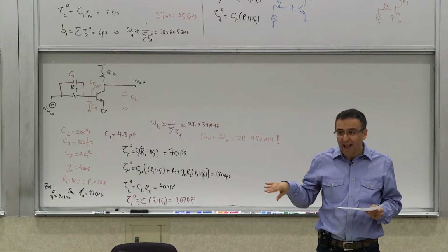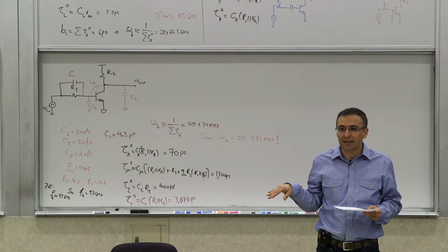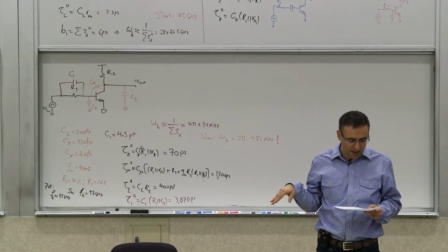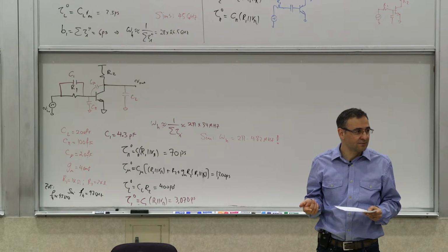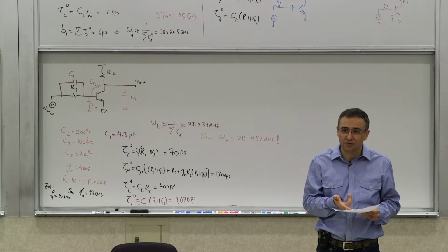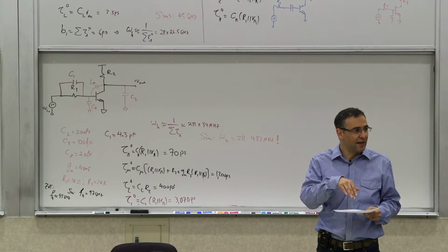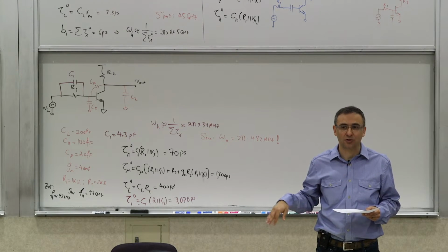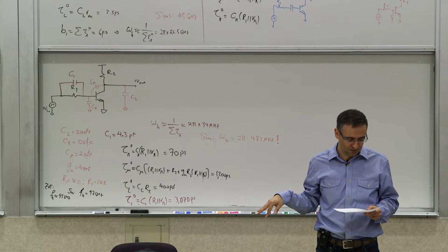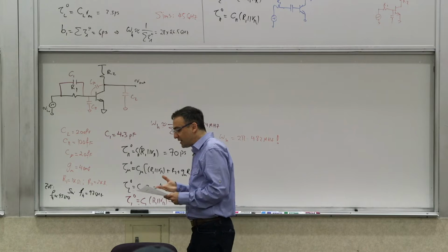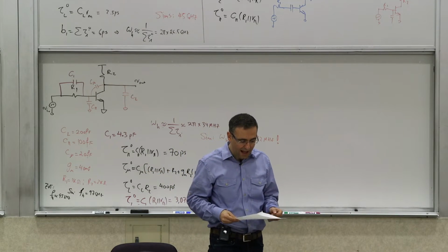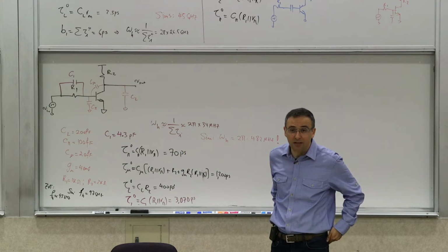Then it becomes flat again, which means that a zero has kicked in. Is this zero left half plane or right half plane? Look at the phase response: the phase hasn't come back up, it actually is added. So it's a right half plane zero. From what you see, a single pole and a single right half plane zero.